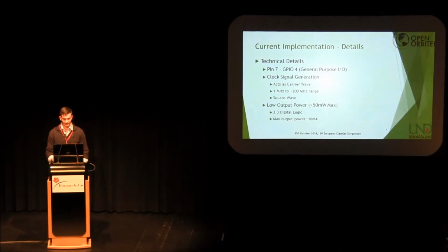Some considerations we needed to take into account was that it was very low power, less than 50 milliwatts. This is due to the 3.3 volt digital logic pins being limited to 16 milliamps of current, and that number decreases the more GPIO pins are connected.